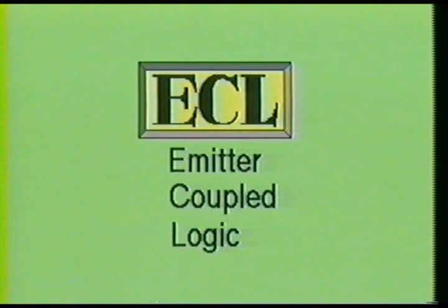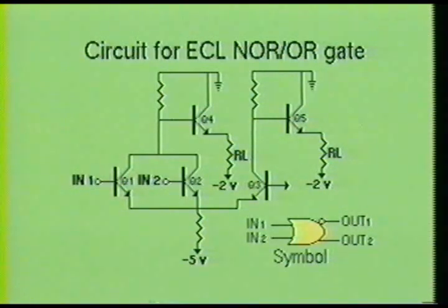Here we see another commonly used digital logic family. These logic devices are termed ECL, which stands for emitter-coupled logic. Internally, the emitter-coupled logic circuits will use NPN transistors with their emitters tied together. Notice in the schematic of an ECL gate, the emitters of Q1 and Q2 are tied together. Transistor Q1 is used for one input, and transistor Q2 is used for the other input. Also notice that this gate has two outputs. One comes from the emitter of transistor Q4, and the other comes from the emitter of transistor Q5.